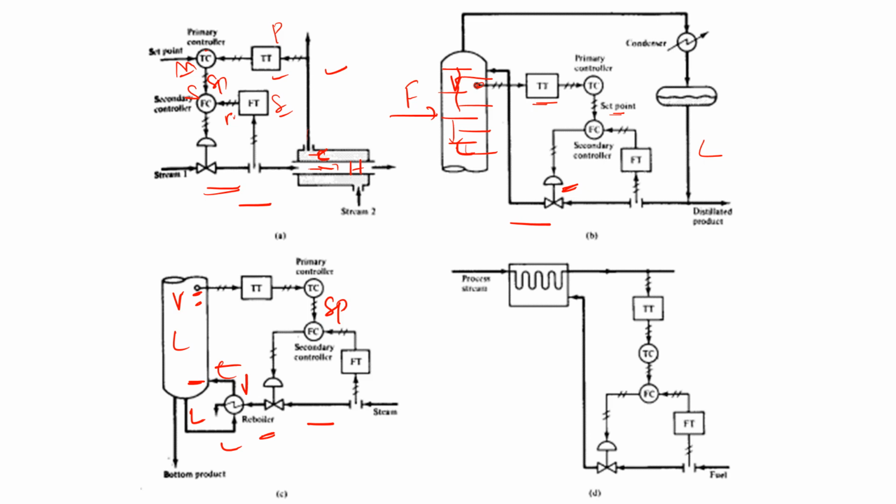So what we do is, before we take an action, first we measure the flow rate of the steam. So this flow rate gives a control variable, I mean the process variable to be controlled, and this becomes a set point. So it compares and it gives the output. Accordingly, the steam given to the reboiler will be increased or decreased. Automatically this will affect the temperature. Okay, so this is one more cascade control. So primary controller, master controller, secondary controller, slave controller, we have two measurements. So this is cascade controller.